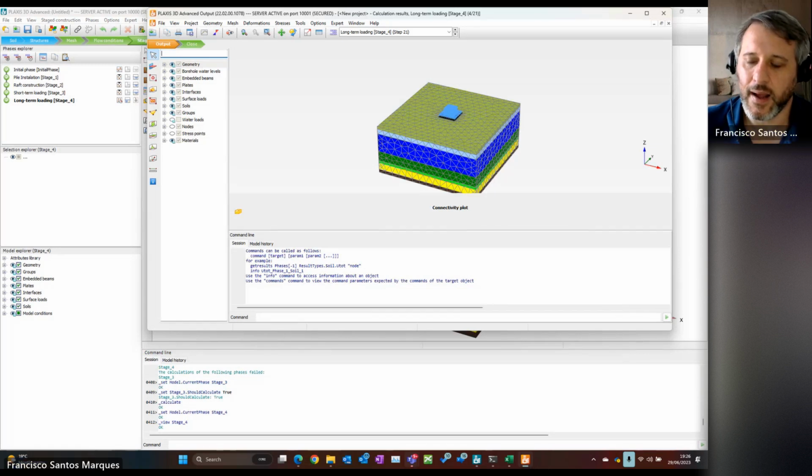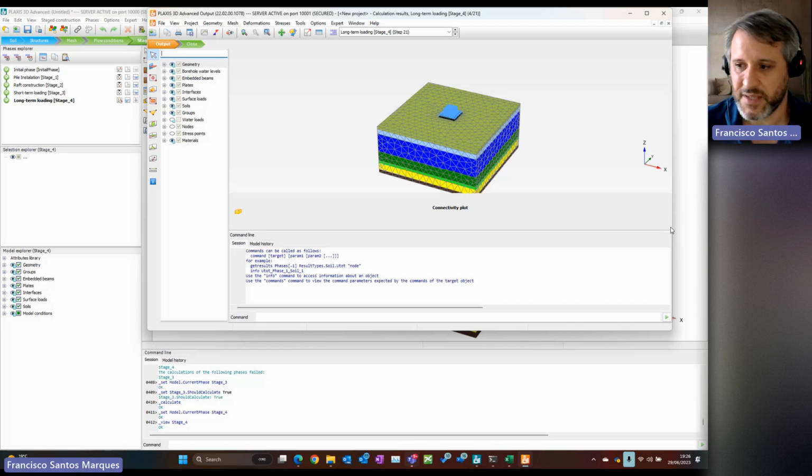The only thing that probably benefits most from the script here is the piles, because it's 80 piles. If you know how to do the commands, you can always go to Excel and try to replicate them. But if it is a large project, or you have piles with different lengths and you have to specify different properties, you can easily end up with 20 or 30 different combinations of pile diameters, lengths, toe levels and tops.